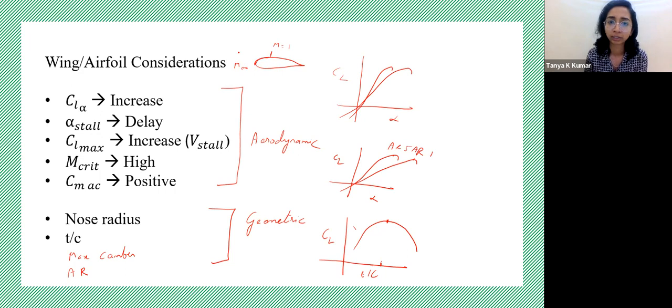Why does it accelerate above the airfoil? So if your M infinity here is suppose say 0.8, and this M infinity in this case would be M critical, if I'm just taking a case, we know that at some point on the airfoil, it becomes Mach 1. That means at some point on the airfoil, the velocity is higher than at the leading edge. Why does the flow accelerate to a higher velocity?